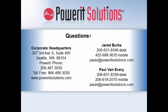So you lose the ability to manage your peak demand level, but you don't shut your operation down. So if the system were to fail during the middle of the night and you couldn't get it back up and operating, you would still be able to continue to meet production demands and requirements. You would just end up having to pay a higher penalty at the end of the month if you set a coincidental peak in your facility during that time period.